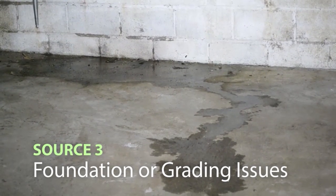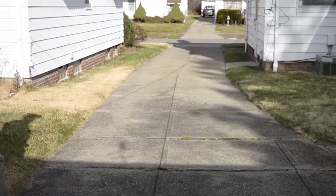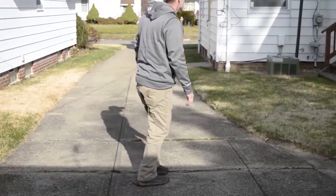Source 3 is foundation or grading issues outside or water falling against the foundation. The ground near the property should be graded away from the structure. Get down on one knee and inspect the grade. If the property is not properly graded, water will flow towards the foundation.